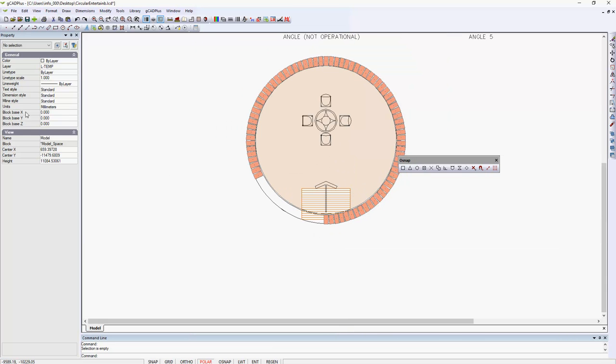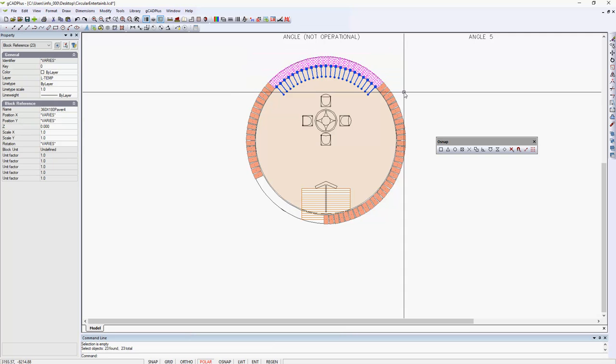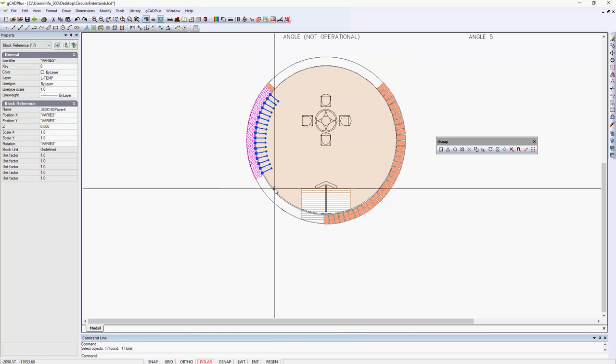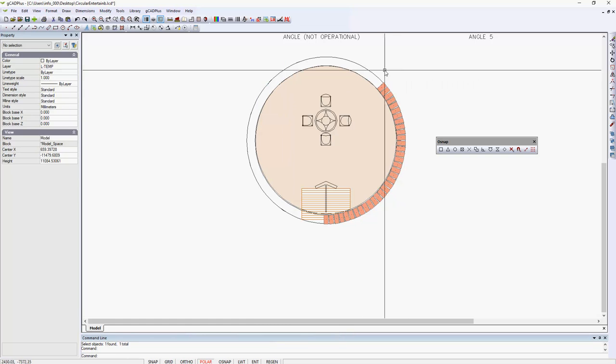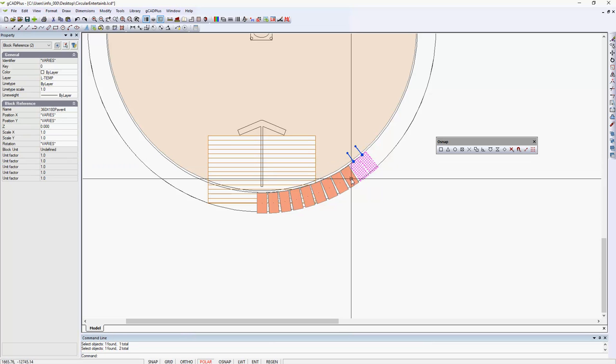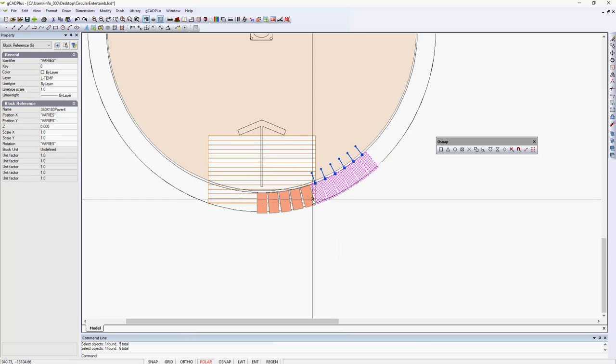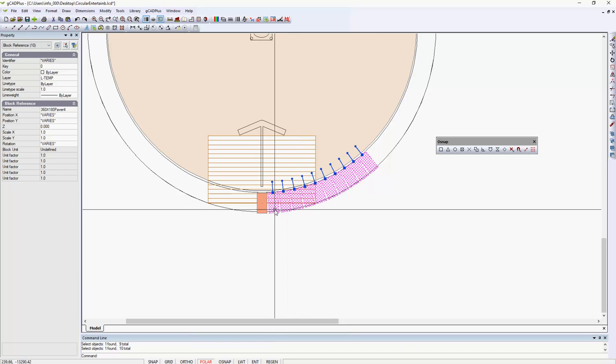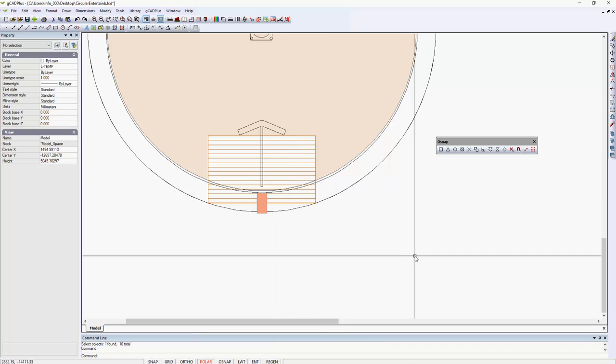And because I'm running on a temp layer, I could very easily select all those paving bricks and just rotate them, but the gap between the first and last is still a little bit big, so let me just erase them and we'll run it again. So we'll use the window option to select those, and it may seem a little tedious to you, but it's a lot easier and neater than trying to position these by hand. And we'll delete those.